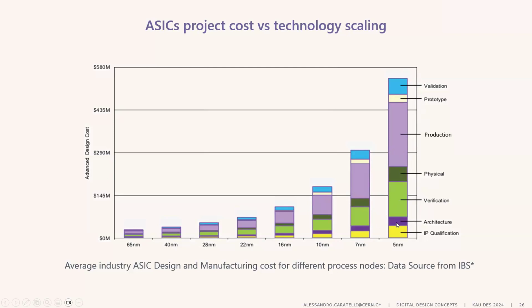For very highly scaled technologies, like below 16, you are going to FinFET instead of using bulk CMOS technology, which requires a larger set of masks for being produced. So, for instance, for the lithography process, you need a larger amount of masks, and this also increases the fixed cost. So it's not only from the fact that the process is newer, but there are also some technical reasons why the process is more expensive. But on average, the trend that you see in the market is that the latest process is always much more expensive. And then after some years, once it becomes more popular, the cost starts to reduce, and the newer processes have this higher cost.